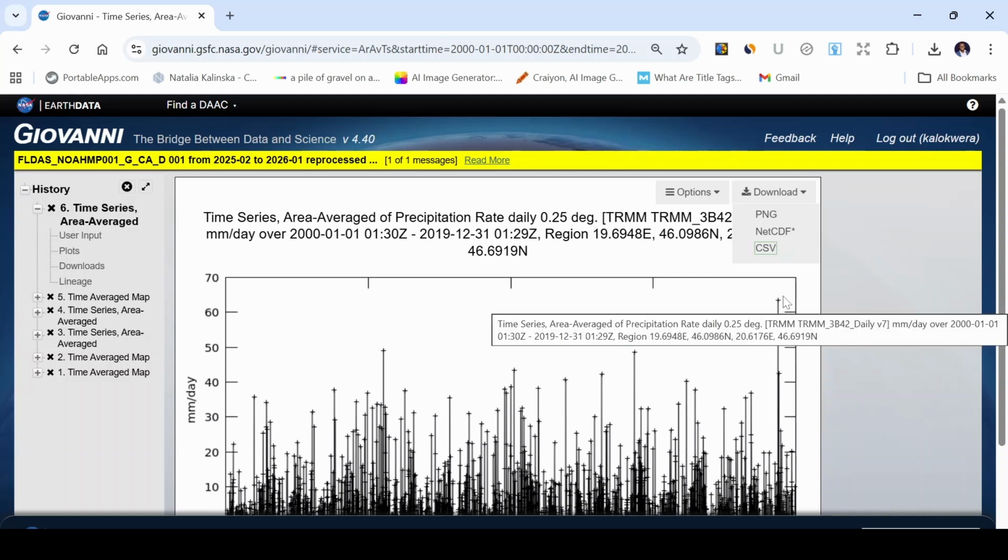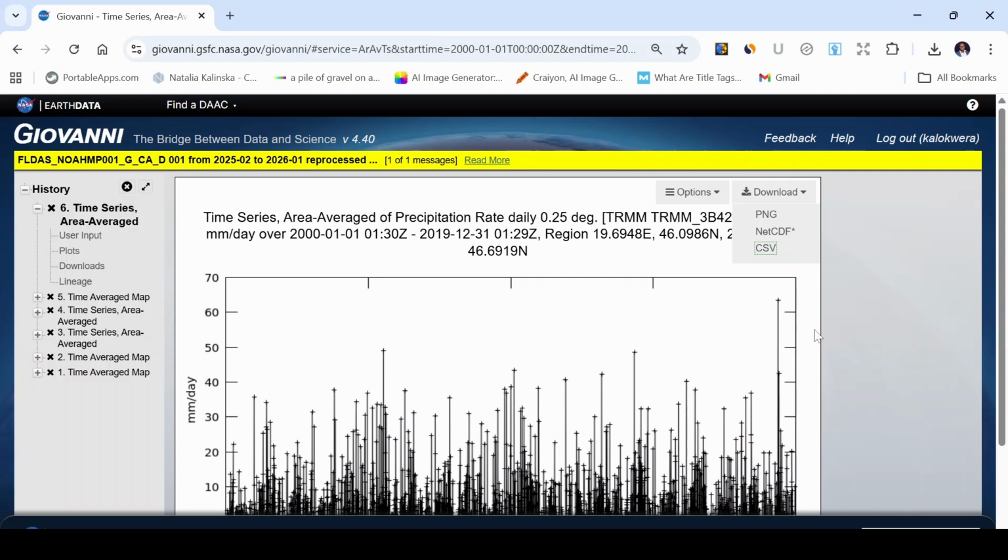This is how I validate my rainfall data. The first step is to compare with gauge data. Where gauge data exists within the project area, I compare long-term totals and seasonal patterns. I make sure I get the mean annual rainfall, the monthly distribution, and the wet and dry season timing. This normally helps me for comparison purposes.